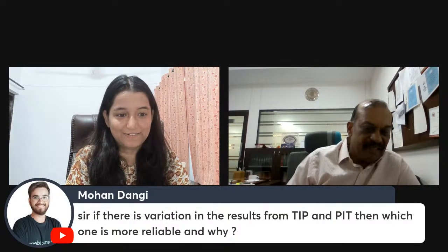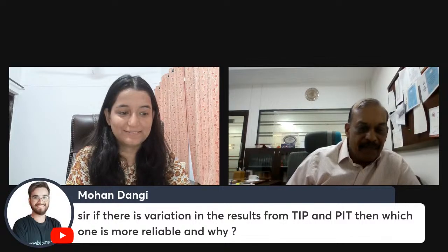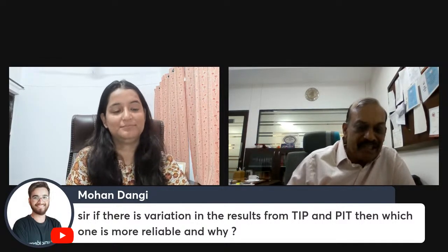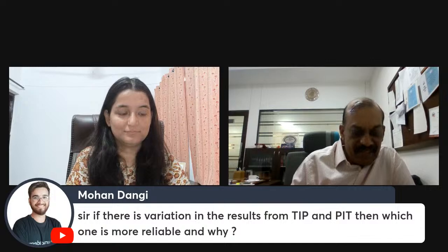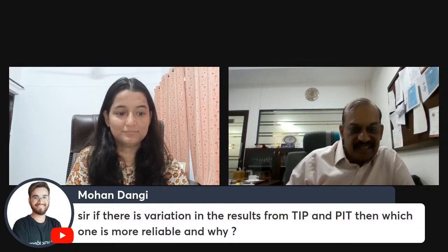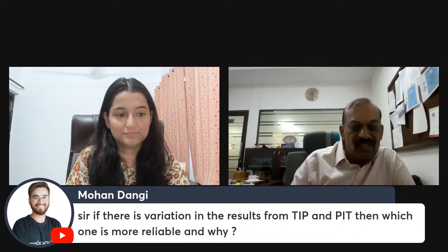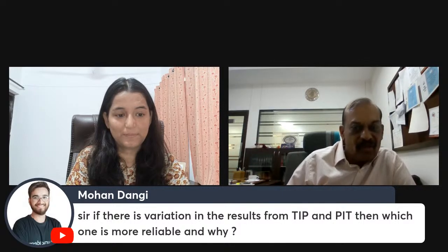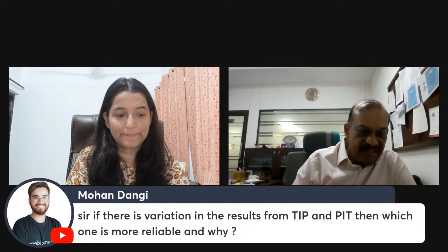Thank you, Azhar. There is a reply from Mohan Dangi. TIP is for thermal integrity test. Oh, yes. Thermal test is apparently very good. I have seen the results of one or two tests, but the only thing is that the thermal integrity test equipment is not so easily available in the country, although some companies have it.